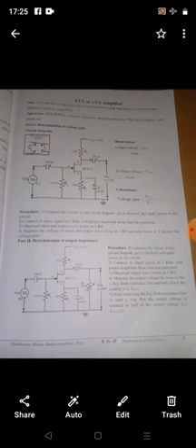We use the FET BFW10. BFW10 is an N-channel JFET. Its recovery time is much faster compared to other transistors. The B means silicon, F means transistor, high frequency, low power, which is a bit random, as a BF can mean a high frequency bipolar transistor or a FET. The W10 part is the manufacturer's designation of it.